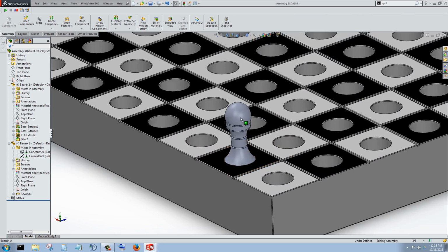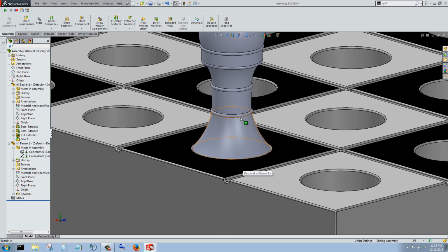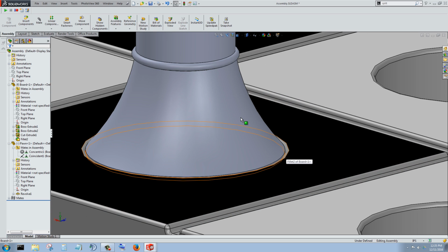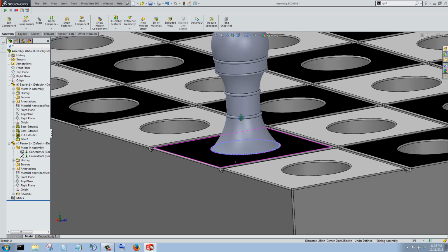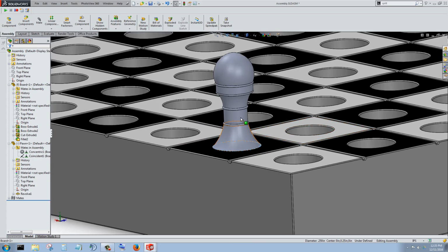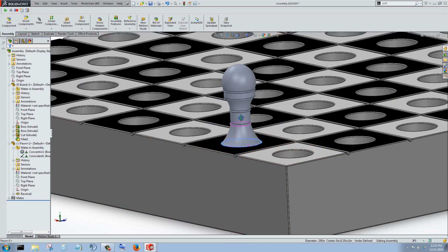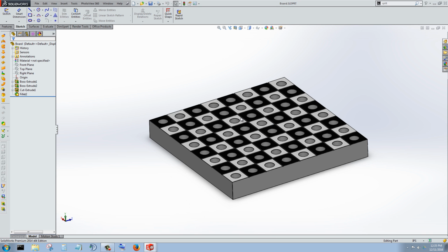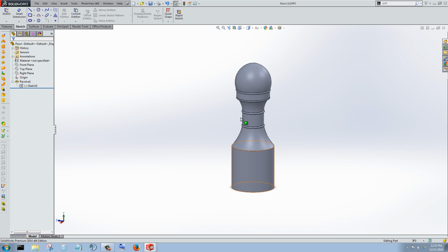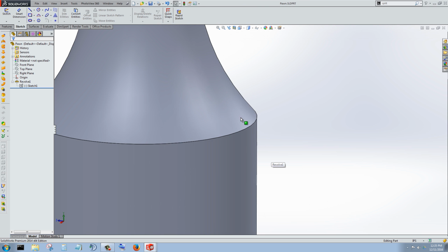It's not bad. I think that I would like to see the foot extend up above the board a little bit to give it a pronounced foot. Right now the foot really doesn't exist. The base goes straight into the board. So what we'll do is just Control Tab. Oh, that took me to the board. Let's get to the part. And so I want to bring this lip up a little bit.